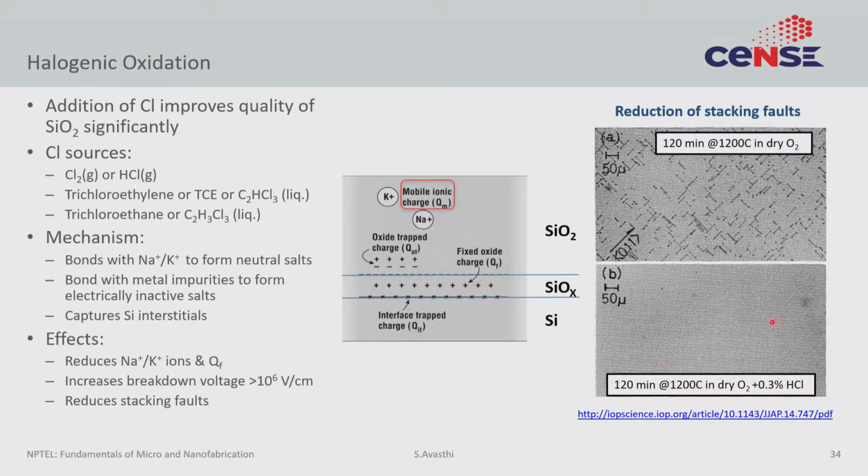Let's talk a little bit about mobile ionic charge and how to remove it. So part of the solution is to maintain cleanliness. We have already discussed surface cleaning techniques: using CMOS grade chemicals, using clean rooms, never touching the wafers with hands, etc., etc.